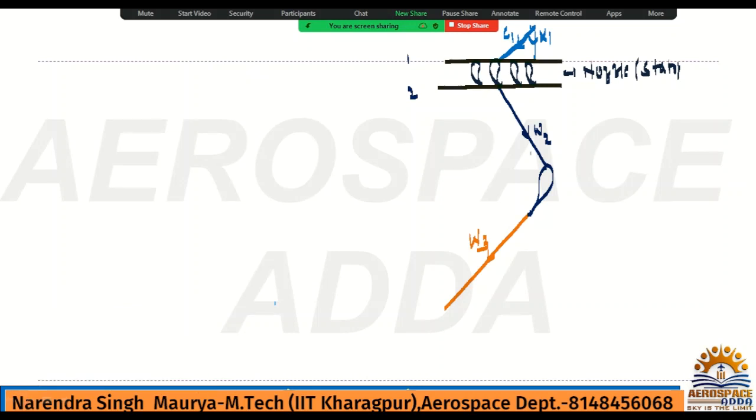All right. So this is W2, relative velocity inlet, relative velocity for the rotor, and this will be obviously axial velocity, and here we have station 2, so this will be CA2. Okay, and this velocity will be absolute velocity, and it will be C2. From the axial, this angle will be beta 2. From the axial, this angle will be alpha 2. This should be very clear. Okay, already I had explained. All right.